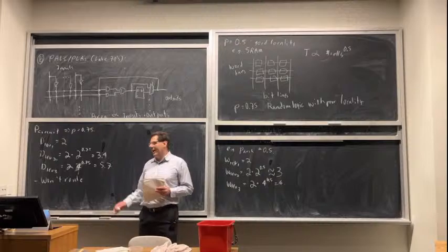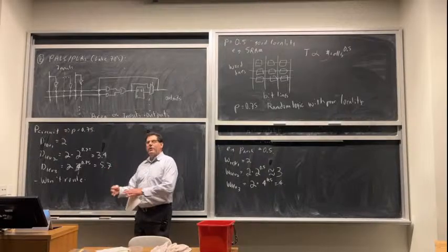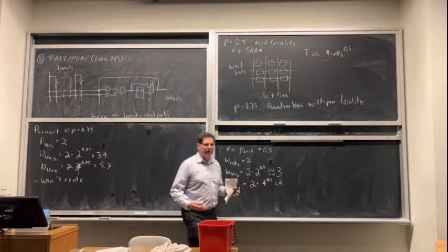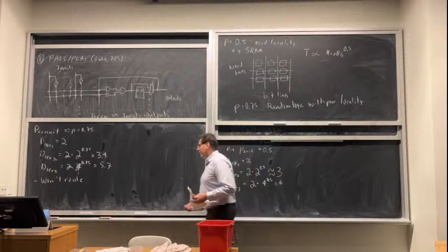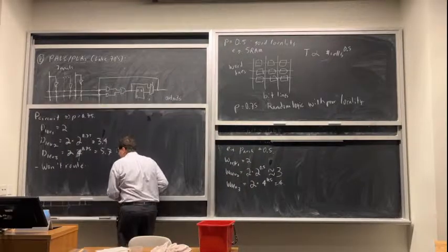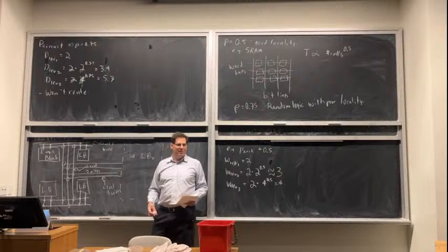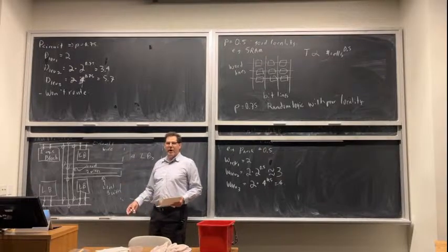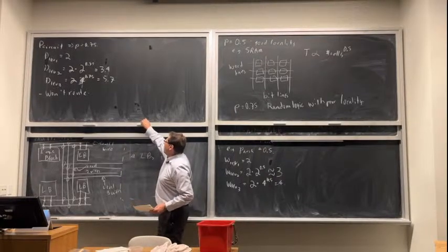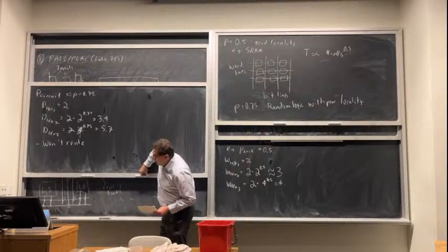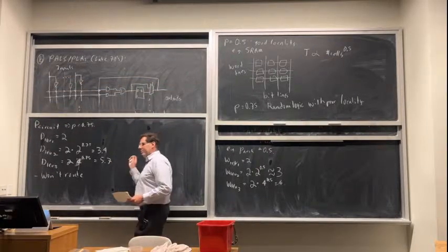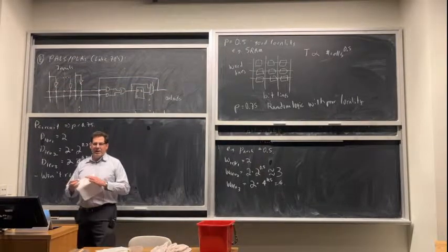Well, I could change my chip. I could say, I didn't build enough routing, so I'm going to go back, and the next time I architect one of these chips, I'll assume a rent exponent of 0.75. I'll make all the channels wider. If this is happening to most of my user base, then that's what I should do. I just need to widen my channels next time because tons of people are having this problem.